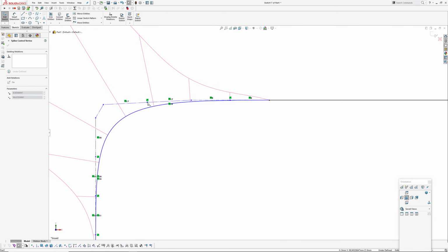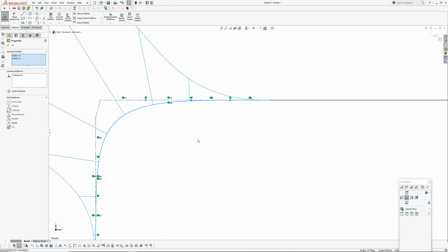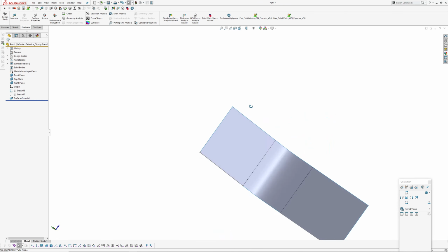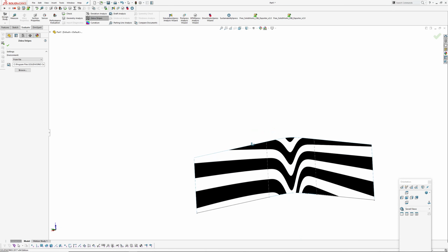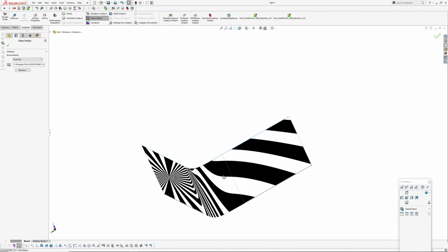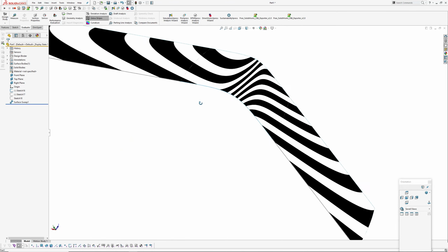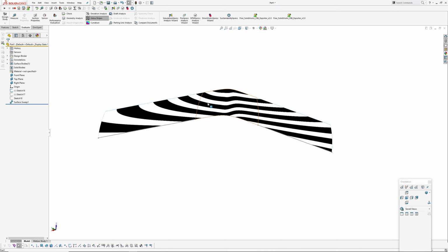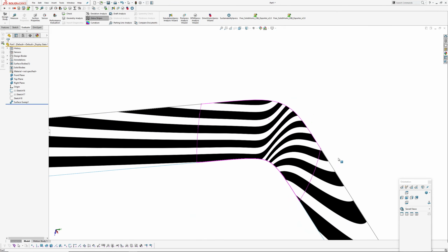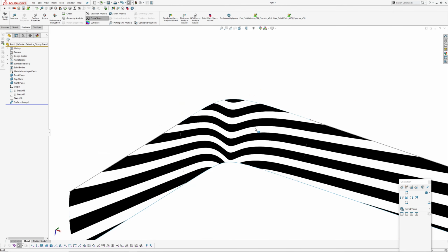Right, so theoretically that's G4, but okay, you got to muck around with the length. Oh, collinear. Yep. Lovely. Okay, so you can do all this with just style spline without having to have the torsion constraint.